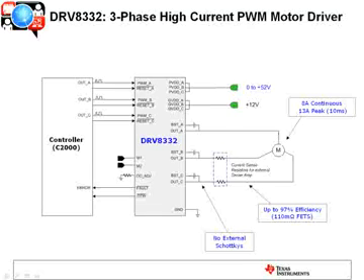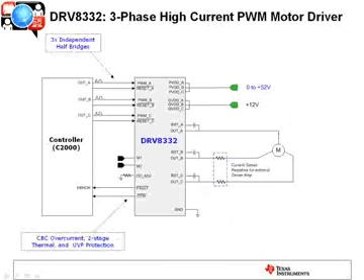That's 110 milliohm FETs, so very low RDS on. The power FETs in this device are very robust. No external Schottkys are needed. I mentioned the 3 independent half bridges. The reset pin is how you tristate the half bridges in this 8332.